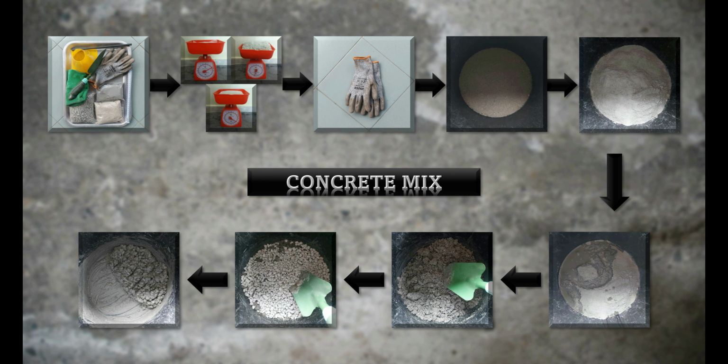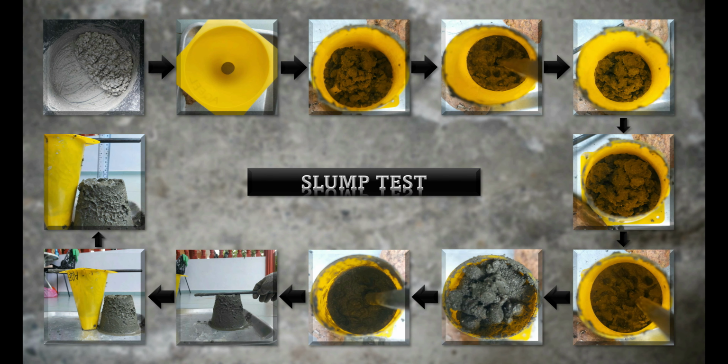The fine aggregate, water, and cement powder are mixed intimately by using a shovel by means of turning over and over repeatedly until the color of the mixture is even. Then, spread out the mixture evenly. 1.074 kg of 10 mm coarse aggregate is added into the mixture and mixed by means of turning over from side to center, while adding another 0.0595 kg of water until the concrete mix is uniform in color and consistency.